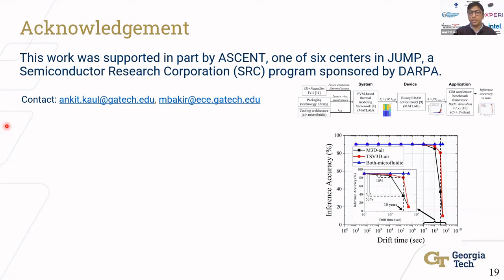One approach is more thermal aware partitioning, and the other approach that the community is looking at is the development of advanced heat spreaders in the back end, or closer to the active tier. For instance, there's research ongoing in aluminum nitride as a potential better heat spreader, which can eliminate the thermal interface material layer and integrate the heat spreader directly to the backside or closer to the device. So essentially, methods of reducing the thermal resistance of the stack, as even Srijit alluded to. These are a couple of areas I can think of.